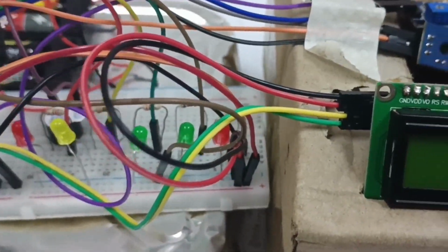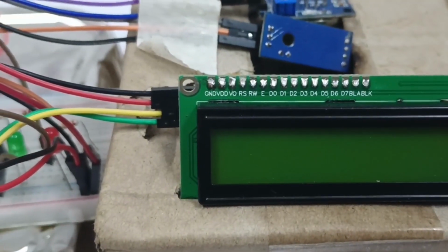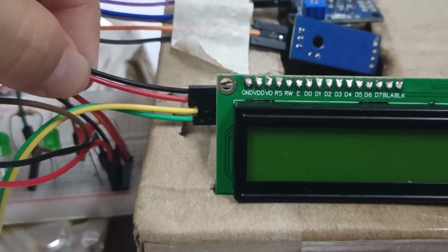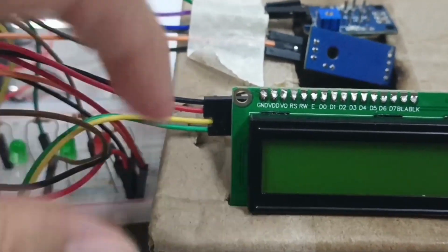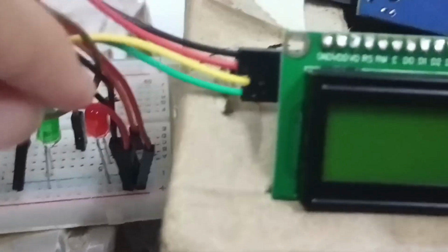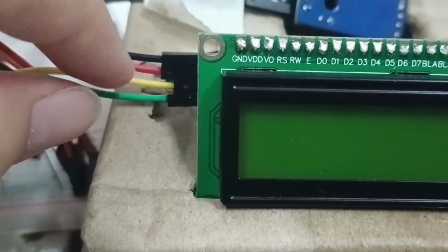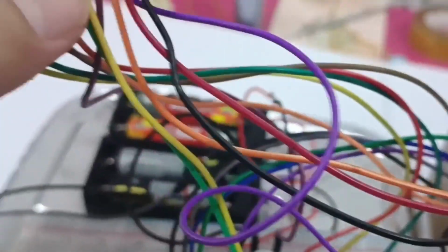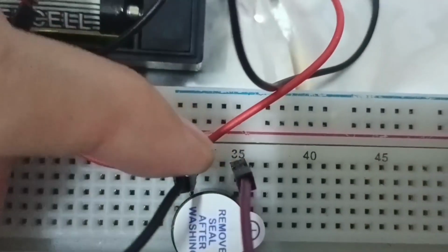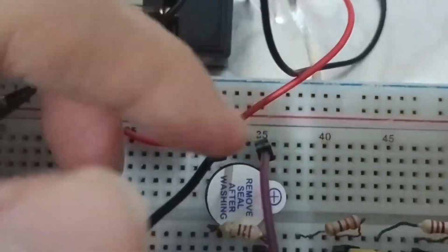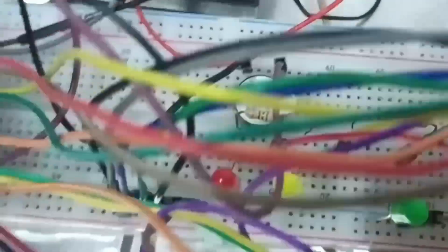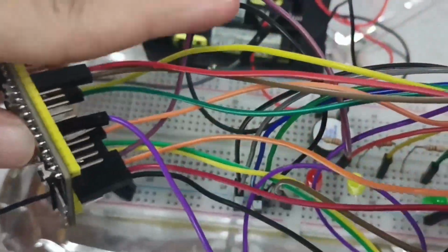And last, the output part. The LCD1602 with I2C module has 2 power pins connected to the VCC and ground, while the SCL is connected to the PB6 and the SDA to PB7 of the Blackpill. Next, the buzzer has the negative pin connected to the ground, and the positive pin to the signal of the controller, which is PB8.